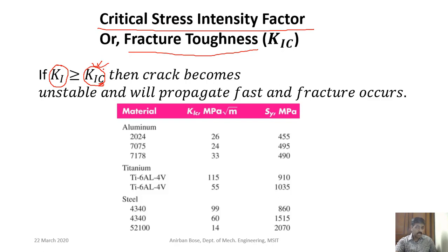This is a material property. It depends on the temperature, it depends on the loading rate or the strain rate, but it is in no way related to the crack and all that. That means it is not dependent on the geometry but on the material. That is the most important thing to remember.